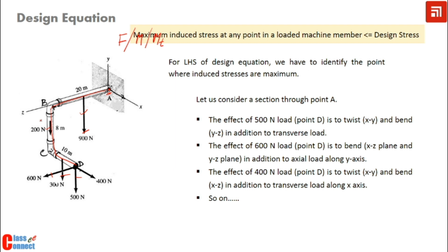That means we have to find out the effect of loads acting at different points at point A. Unless we are able to find out the effect of loads at point A, it is not possible to calculate stress at this particular point A, and if we are not able to calculate stress at point A, we are not able to write down the design equation properly.